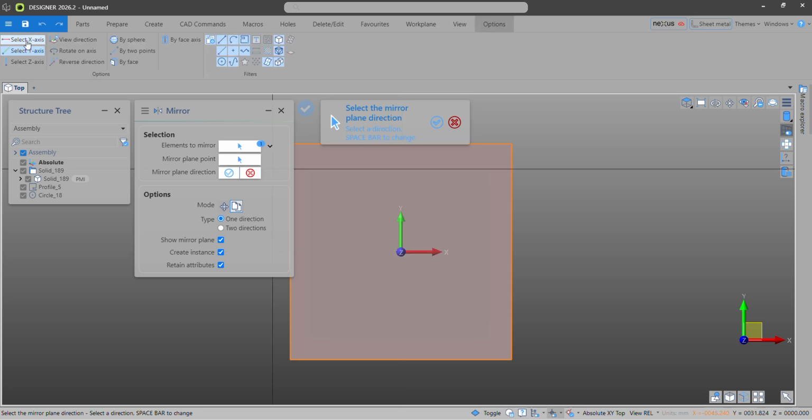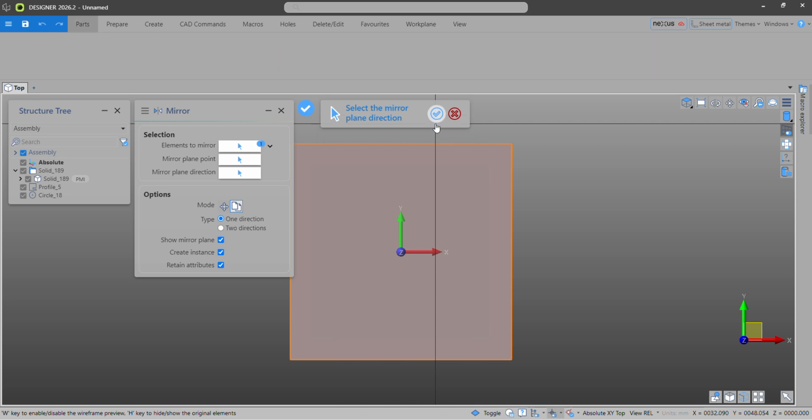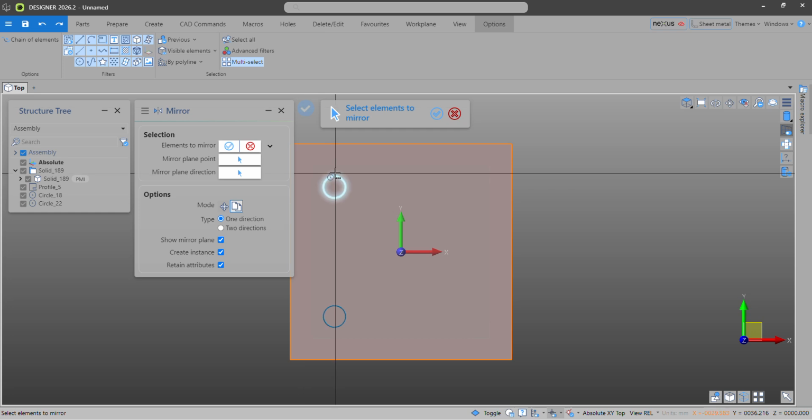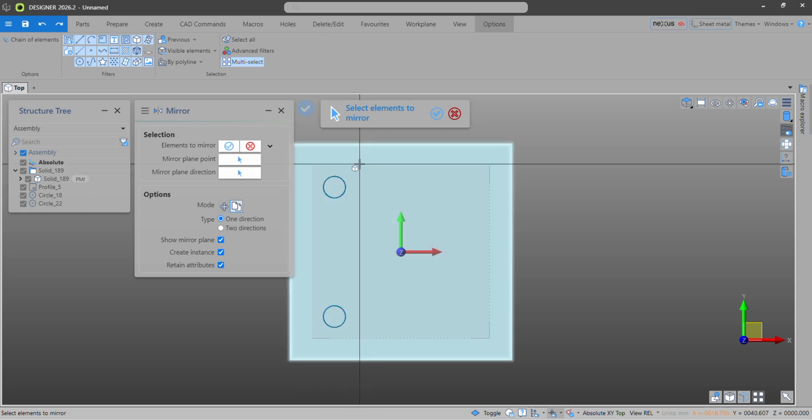All right, mirror the X or mirror the Y. Now it's a little bit hard to see, but hopefully what you'll see is it's changing direction. That's telling us where those holes are going to go. So there's actually a little line, another arrow in here telling me it's going to mirror like that. So when we go OK, accept, bang, I've got my two profiles added. Now I've got to cut them yet, but you can see how that's going to work.